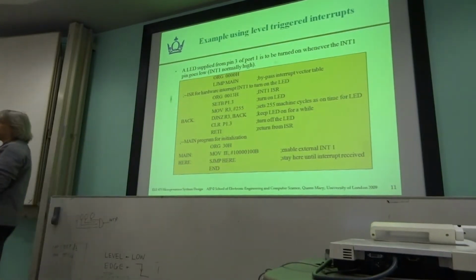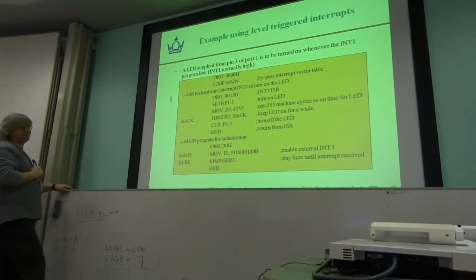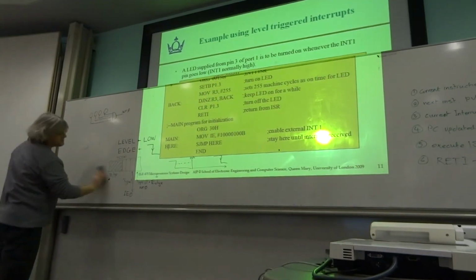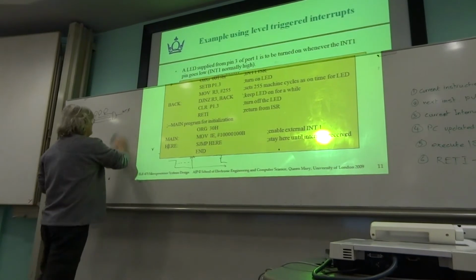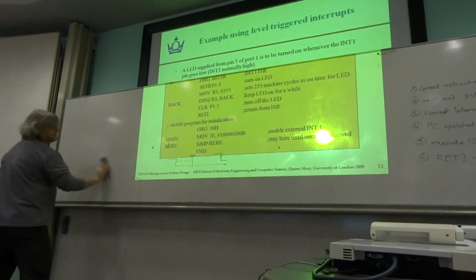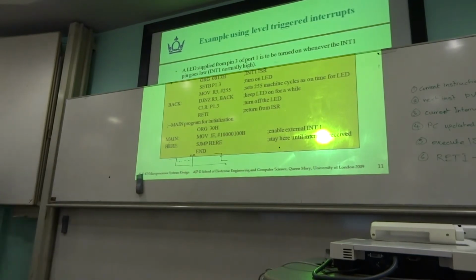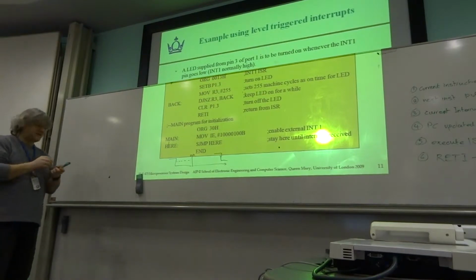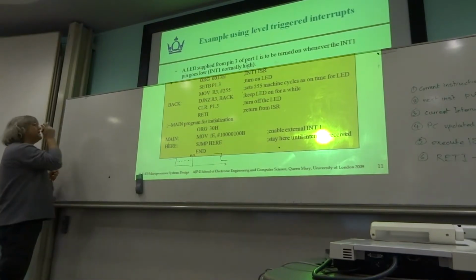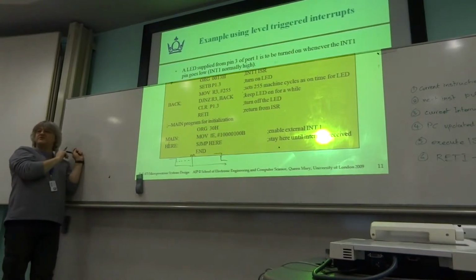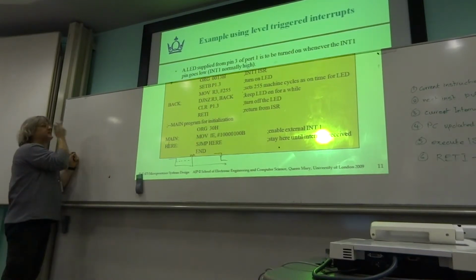So what you might often do, if you want to play safe with your interrupt routines, because you don't know where in the main program you are at the time the interrupt takes place. That's the whole point. It happens whenever this event takes place. So a common practice when you invoke an interrupt routine is to start it with something like this.